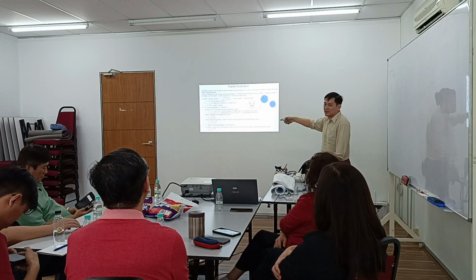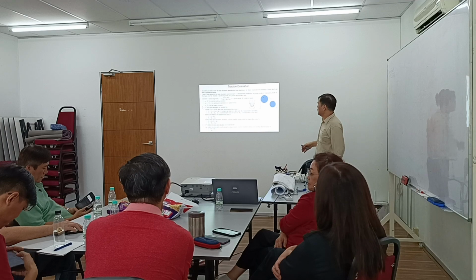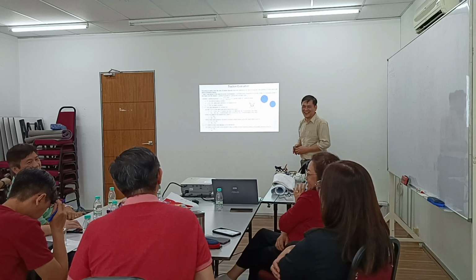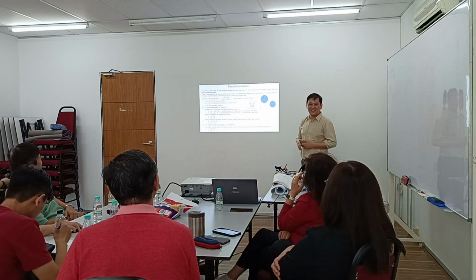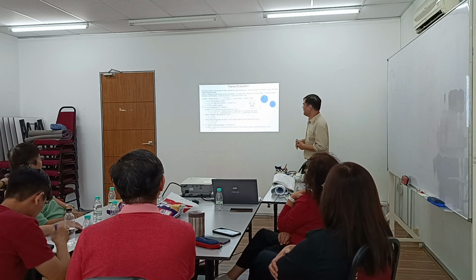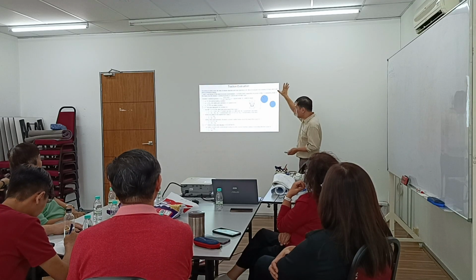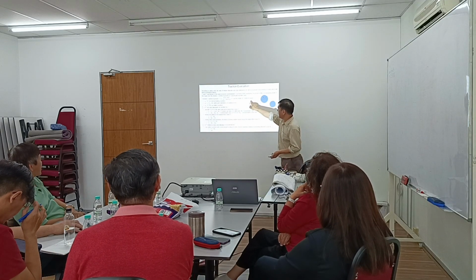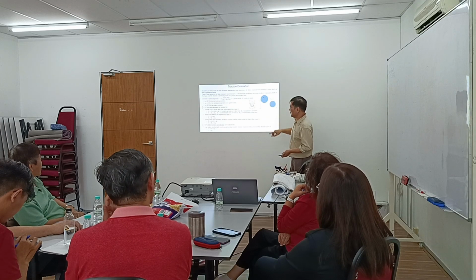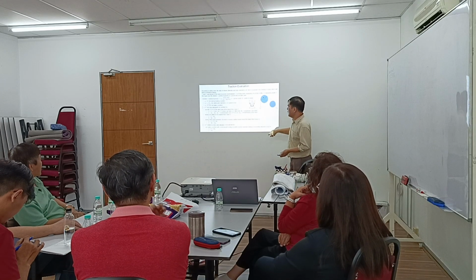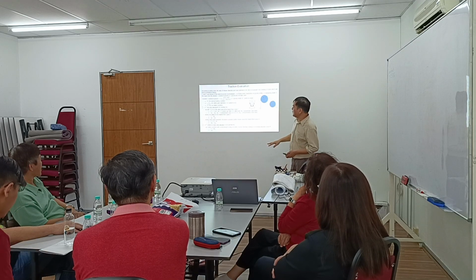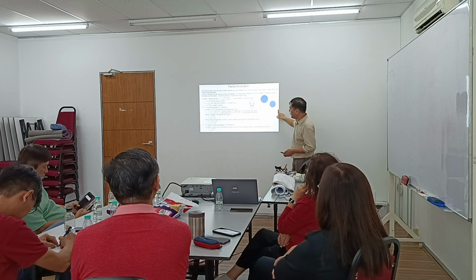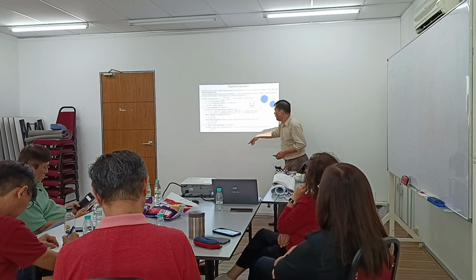So the traction evaluation, all these are calculations. Don't worry, just to let you know. We need to ensure that this angle, which is provided by the supplier, meets certain conditions. Then the tension of the rope on the car and the tension of the rope on the counterweight have to satisfy the traction requirement.